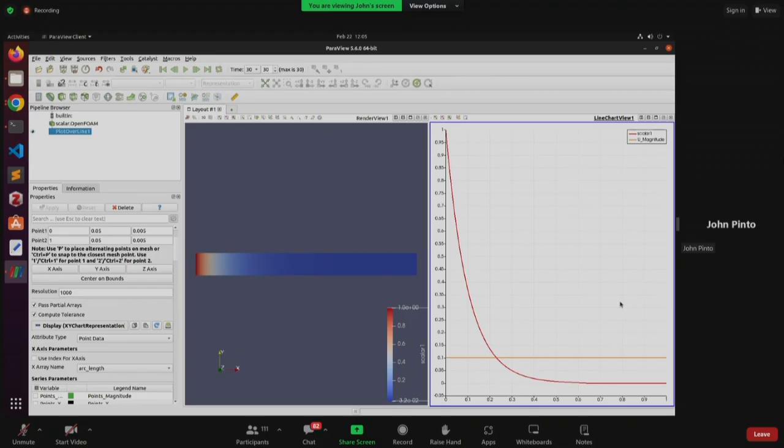In my batch reactor, I was getting the exponential decay with time, but now we have imposed the flow. Now we are getting exponential decay with space. So the concentration at the start is 1. As the reaction is proceeding, scalar is moving ahead, and the reaction is proceeding in time as well. So I'm getting the scalar concentration with space. That means my advection is also working fine. It is advecting the scalar properly. Otherwise, this wouldn't have been proper.